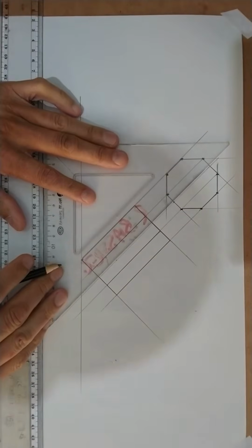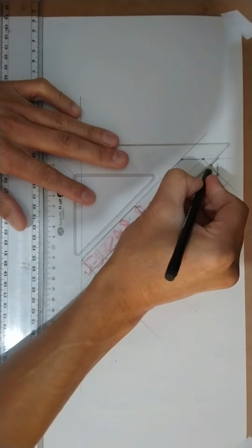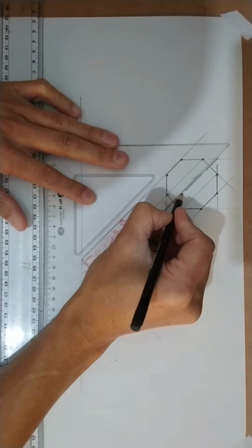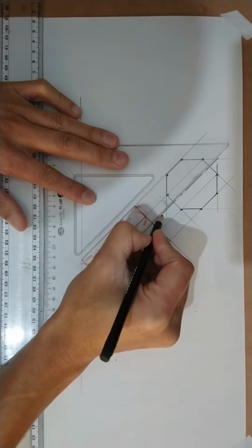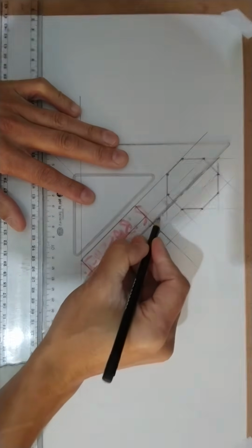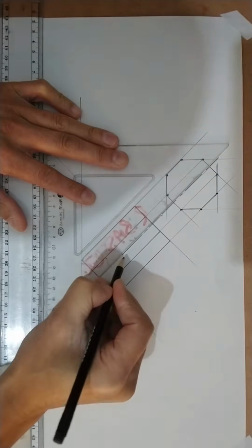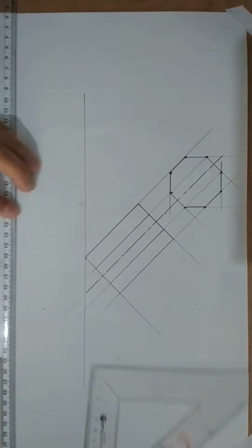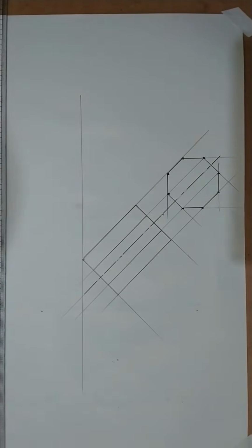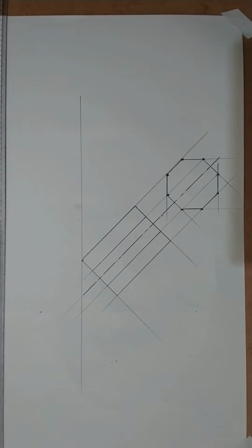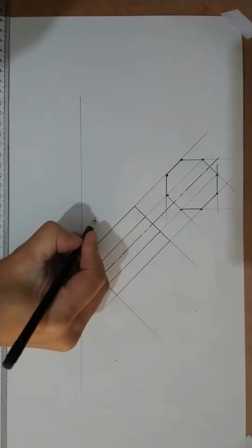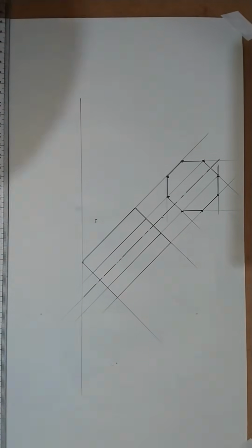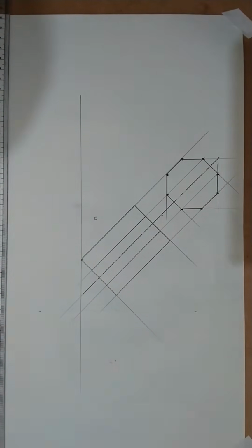It's very important to put in your center line. A center line is a long, short, long, short, long, short line. Very important, you do get marks for that. Right, so it starts with a long one and it ends with a long one. That's my center. And there you've completed. Remember, this is 45 degrees here. Okay, and that's a 45 degree angle.